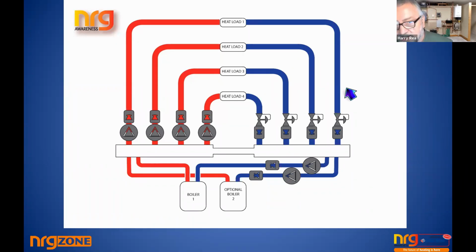And you get guys saying, my motorized valves have failed. And what actually is happening is, the hot water is passing underneath the return pipe looking upwards. It drifts up through the center of the pipe. The wall of the pipe cools the water, and the outer water falls back down, and you start to circuit within the pipe, a one pipe circuit, and then the heat reaches the radiator and it's off. The heat travels along the top of the pipe. It loses heat in the radiator, falls along the bottom of the pipe and down the edges of the pipe, and you've got a perfect circuit through one pipe.